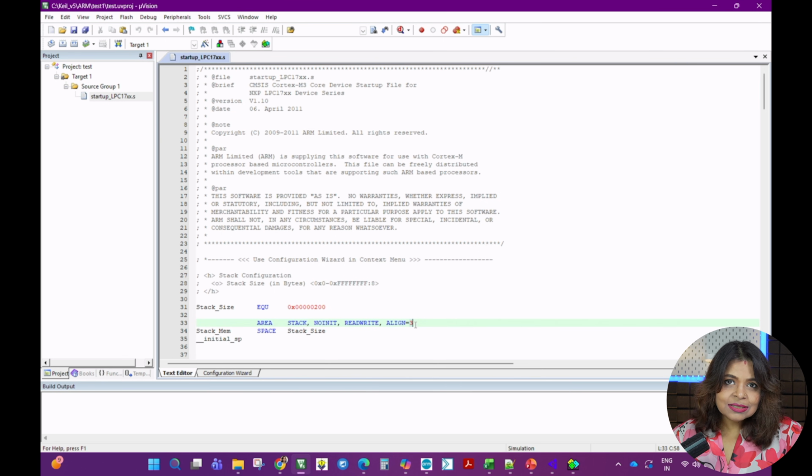Through this startup code, we define the vector table telling the processor, if some interrupt or exception happens, where to look, at a specific address in the flash, to service it. Probably I'll touch on interrupts again in the next video. I have done a detailed video on how exceptions or interrupts can be handled on the same device, LPC1768, so please refer to the video on this link for more information.